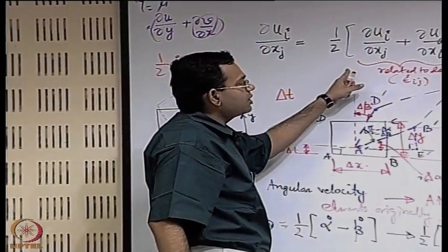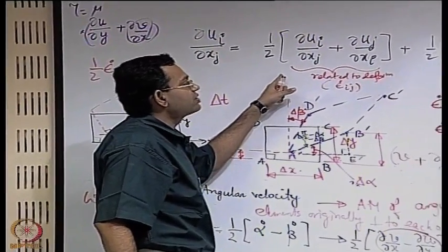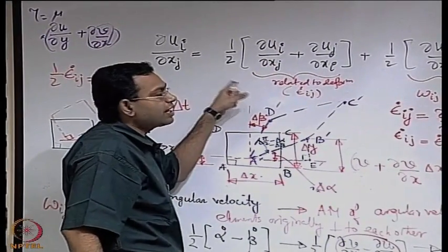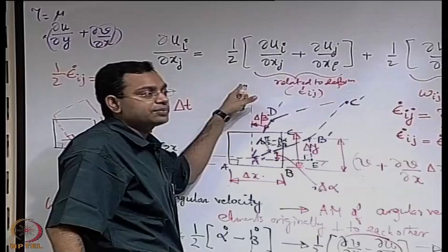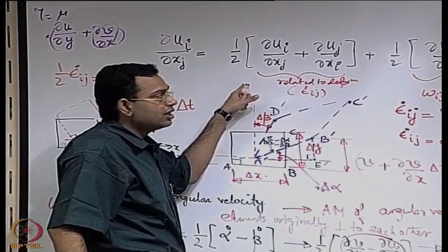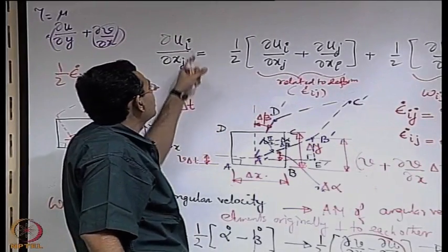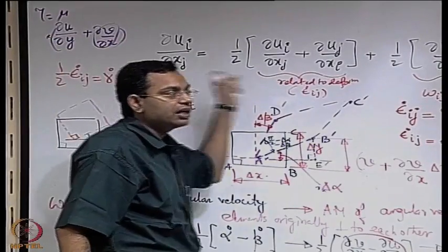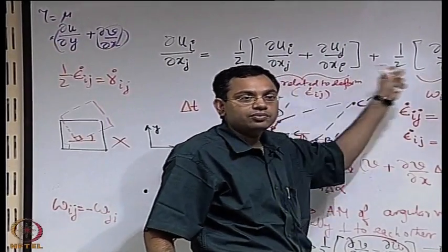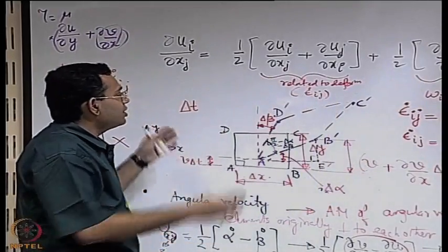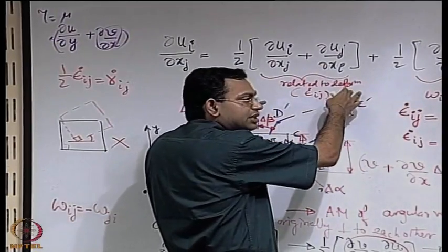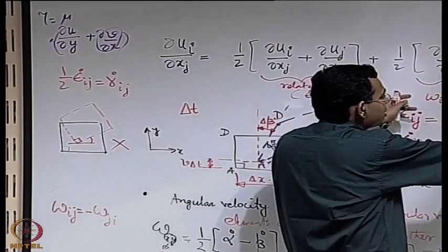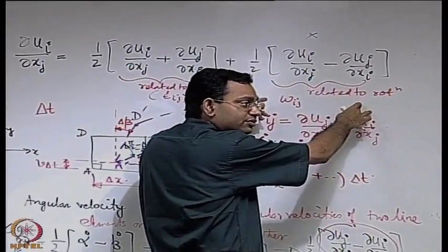The other important observation is that although it looks something which is non-trivial, but actually there cannot be a more trivial expression than this, because it is just like you are writing a form, every matrix can be written as a sum of a symmetric and a skew symmetric matrix, and that is what we are trying to do. So eventually that symmetric matrix is being represented by the components of the angular deformation, and the skew symmetric matrix is represented by the components of the rotation.